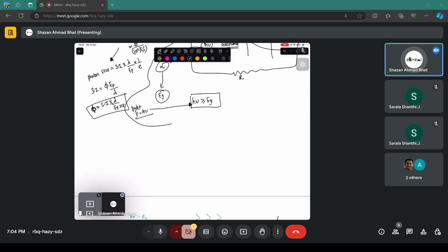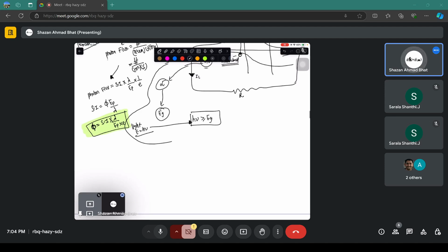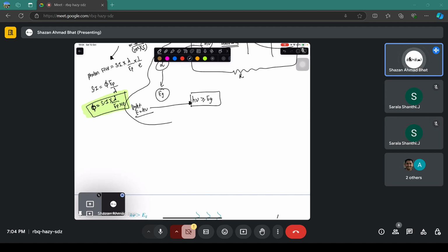Why would the energy gap come into this photon flux concept? Yeah, that makes sense. Because in order to compute the number of photons coming from a source, why do you need the energy gap? You just need the inputs of the light source, and the inputs will be the wavelength of the light, the energy of the light, and the spectral irradiance. That will give you the flux.